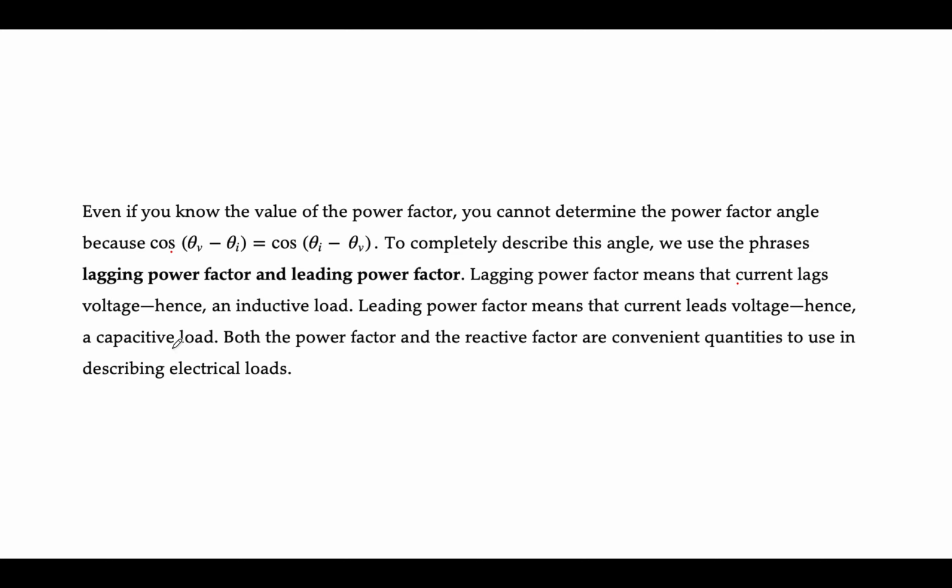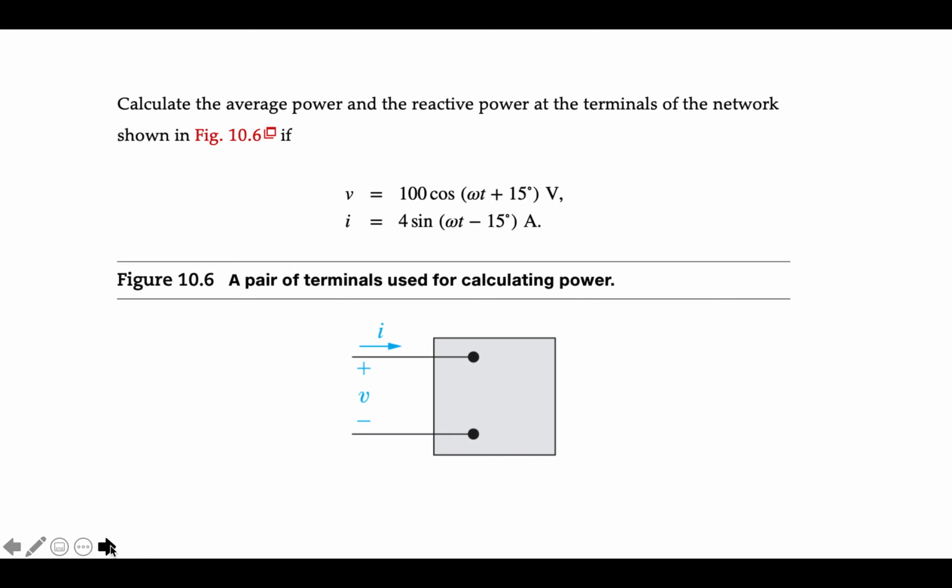So it's important, if you're going to understand what your load is, that you can't just take the power factor. You also need to know whether it is a leading or lagging power factor, and you need to remember that leading and lagging are adjectives that define the current. So the current lags, the current leads. That's how the definitions are made. Why? Because when we originally set this up, we set it up with the reference of the current phase angle being 0, and we're using standard complex plane notation to understand leading and lagging angles. So that's why it's defined the way it is.